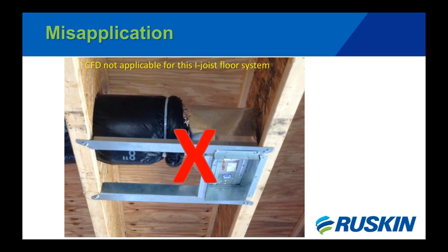Secondly, we have a radiation damper. Now, I will give them credit. They did at least choose the right type of damper, so they had the right thought process. But unfortunately, since the radiation damper hasn't been approved for this, on top of that, they have the damper close to the wood member. So you're going to have charring much faster because you have metal in close proximity to the wood. Even the approved radiation dampers in 2x4, 2x10 and 2x12 wood joist floor systems always have to have the blanket wrapped around the plenum boxes because in most instances you're going to have a plenum box up there.